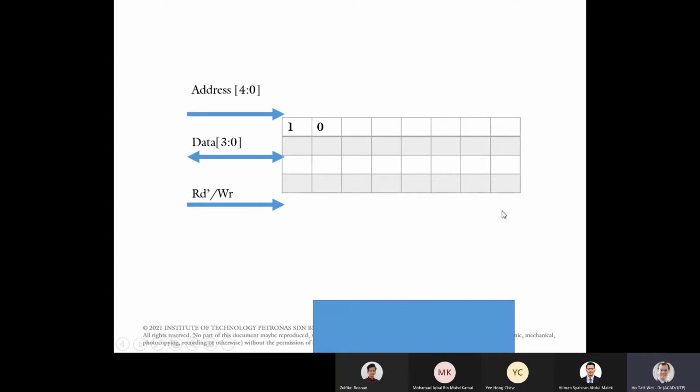I don't have to go through the row access for each bit. Because of the nature of the DRAM, it always reads out the whole word line into the sense amplifier, and then chooses one bit there. So if it's already there, I can be faster and read out consecutive bits. Do you understand that part?